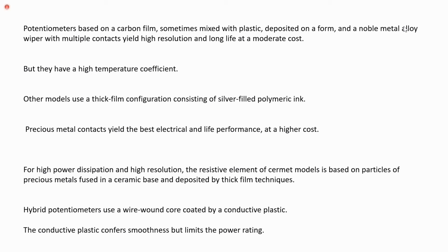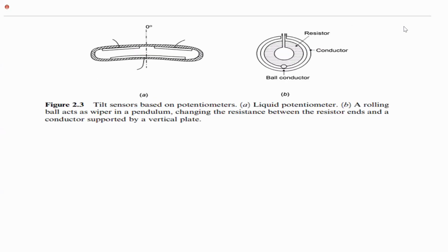For high power dissipation and high resolution, the resistive element of ceramic models is based on particles of precious metals fused in a ceramic base and deposited by thick film techniques. Hybrid potentiometers use a wire-wound core coated by a conductive plastic. The conductive plastic confers smoothness but limits the power rating.